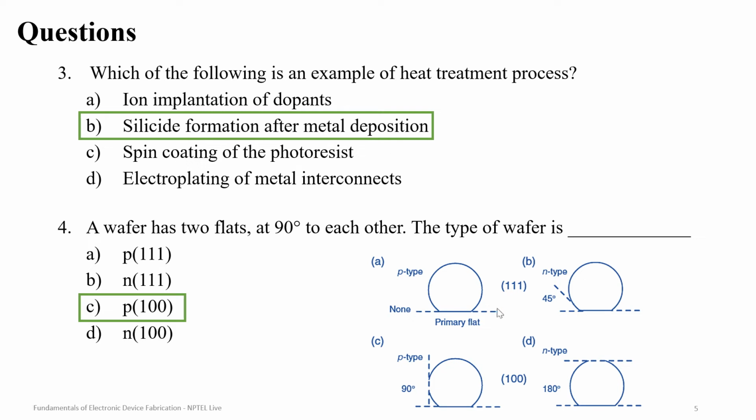Whenever you're using an n type or a different plane, say this is a single crystal, right? Each single crystal will have one particular orientation, and that is given by these indices, that is 111. So one flat only means that your material is P type and it is 111 orientation.